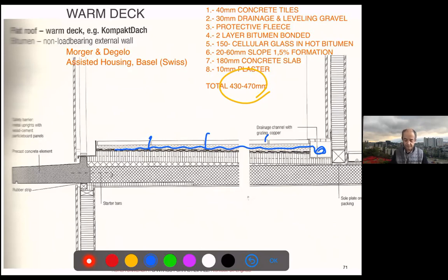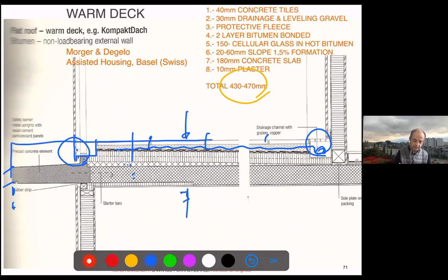Okay. So interesting to have this kind of trench at the end, and very intelligent to have this thin cornice. You see always a dripper, to have one folded stainless steel or aluminum plate at the end, right? See always how you avoid having anything perforating those layers. You always put handrails in other places which are solid. So instead of having a very thick front of the terraces, you have a very thin vision of those terraces.